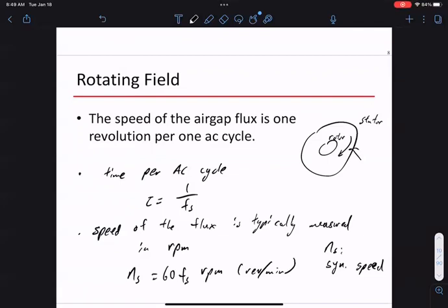Is this a fast or slow speed? Think of the gear from the gearbox perspective. This is very fast from a gearbox perspective. If you have a typical turbine, the blades turn at 30 RPM. Now if I had to match the synchronous speed, I have to match it at 3600 RPM. That makes your gearbox life not very simple, pretty complicated. So the synchronous speed sometimes is too high to use. It just turns too fast. I don't want to convert a mechanical torque at low RPM to a mechanical torque of RPM this high.